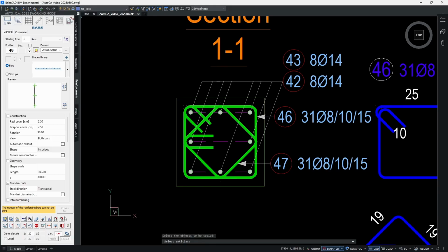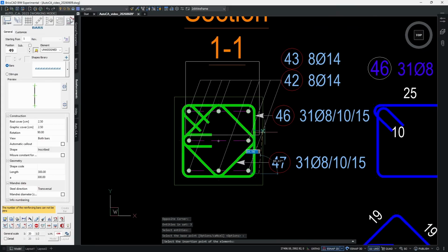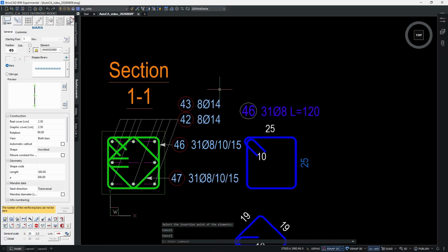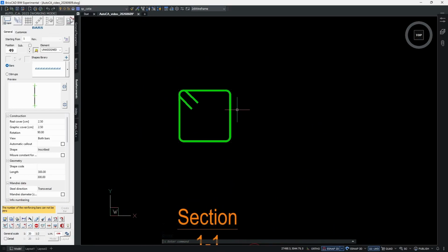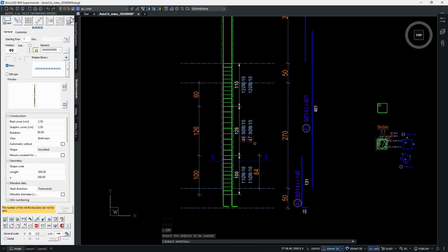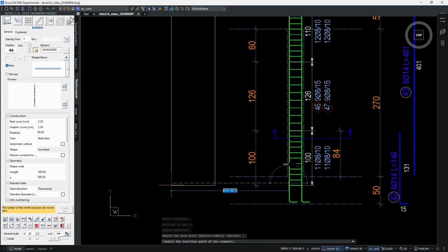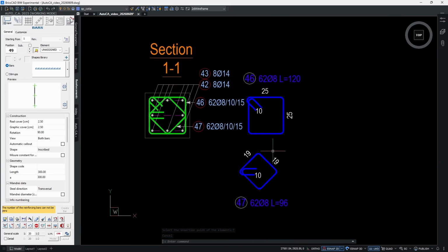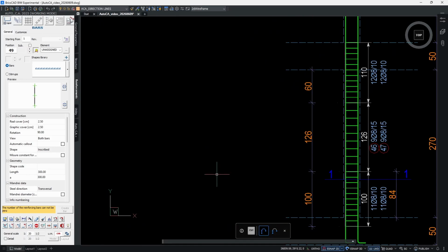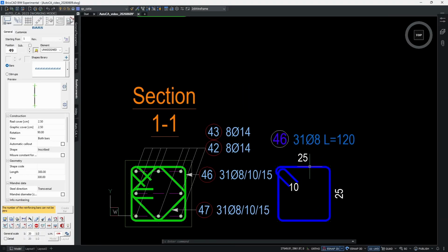It's very important. So when I only copy the inside bar, the quantity won't change because the inside bar isn't counted. If you copy the inside bar distribution though, then the number will change. Now it's 62. If I delete these, then they will go back to 31, yeah, as you can see.